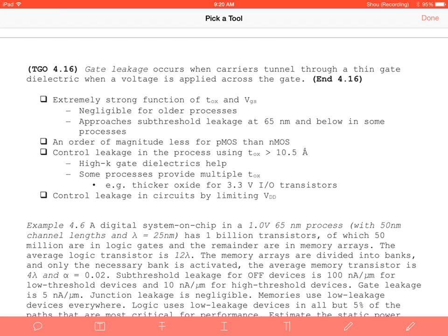There's the problem where somebody designed an improper NOR gate or improper NAND gate, and the reason is they had the NMOS transistors in the pull-up network and the PMOS transistors in the pull-down network. NAND and NOR gates also differ in parasitic delay as well as logical effort. All of these go into why NAND logic will ultimately win out.